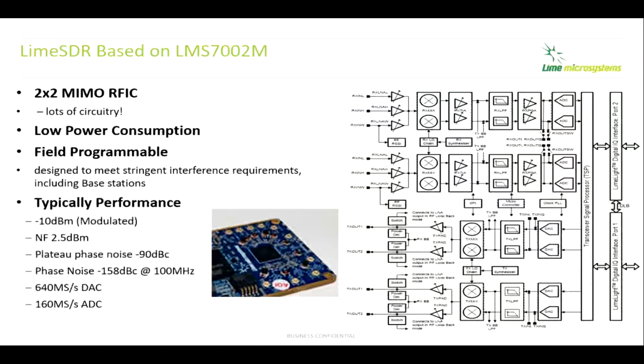I could talk about our transceiver. It's a very complicated animal, and I think this is probably true for most of the radio chips used in software-defined radio. They're highly programmable beasts. We like the term field programmable, which takes on a whole new meaning here, of course. And we're obviously looking for low power consumption, and for today's applications, you don't just have a single channel radio now, but you actually have what's called MIMO, where you would have one, maybe two transmit channels and two receive channels working on different antennas.